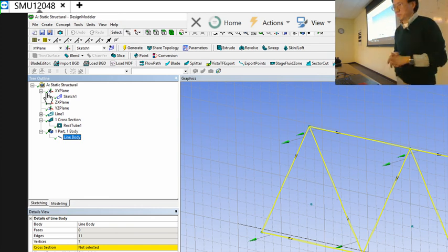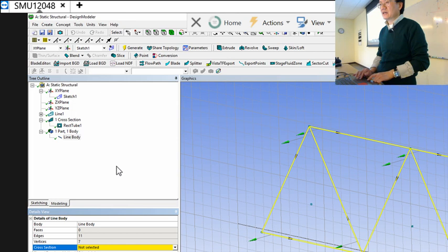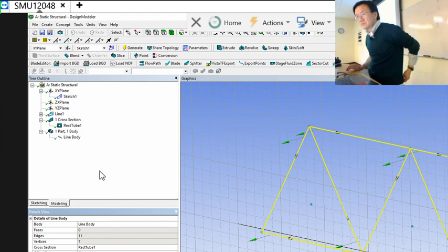Once you select that, you will see your cross-section ask you to choose is highlighted. You go here, click, you will see this. Then there's a drop-down list. You see your rectangular tube 1 is over there, and click. Then that cross-section applies to your structure. Make sure you follow. I slow down here intentionally.